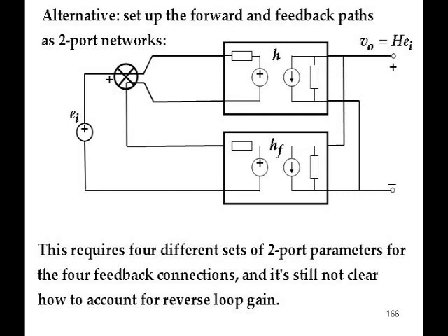And what is done in the books is the reverse transmission of one path is simply added to the forward transmission of the other one. Or it is simply ignored. Well, that's okay to do that, but there's a fatal flaw in the whole process. Even this model is not accurate, because the forward path model ignores totally common mode gain.